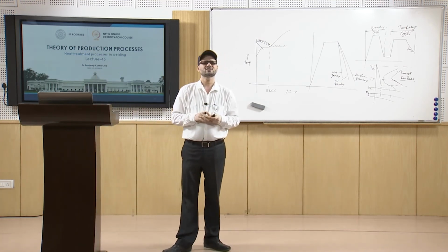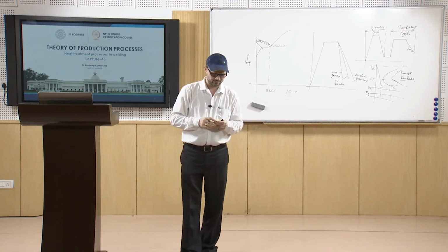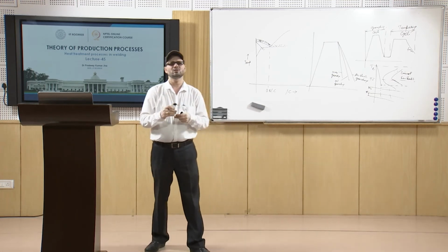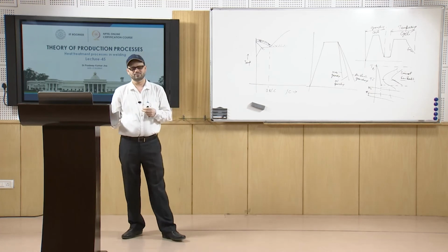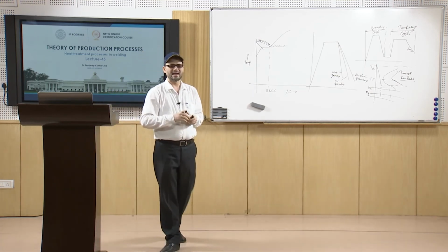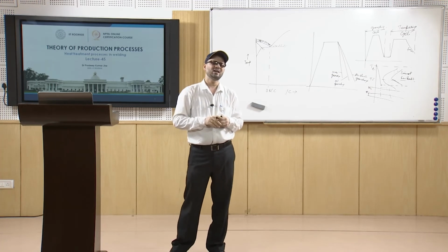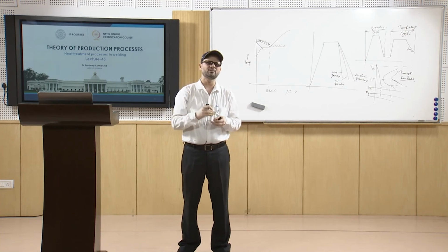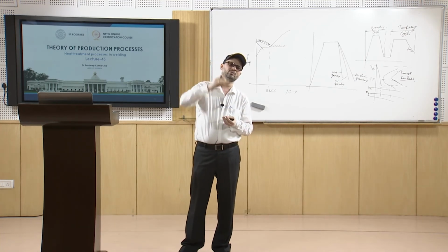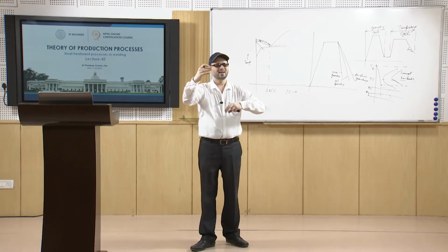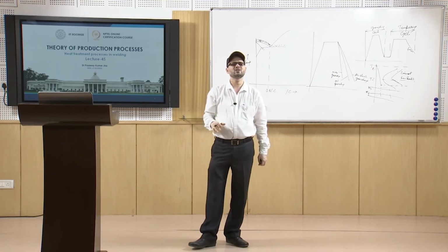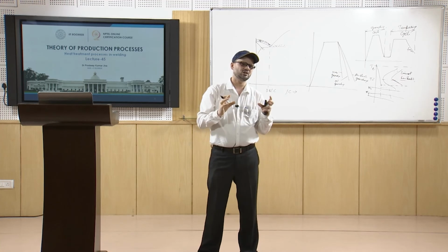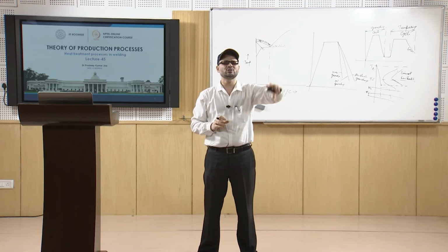Next, we will discuss something about the aging treatment. It is a type of treatment required for certain materials where some phases are super rich in solute at room temperature. Especially in such materials, we do the solution treatment. We go into the zone where solubility is more, and from that zone we quench fast, so that the solute is super rich.